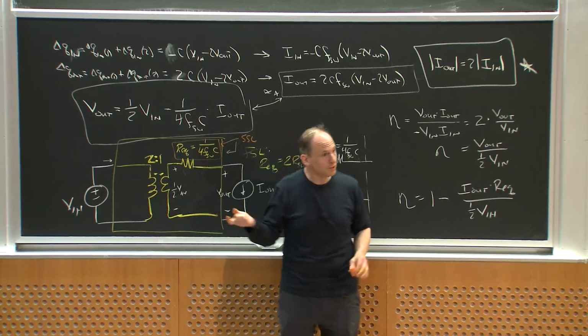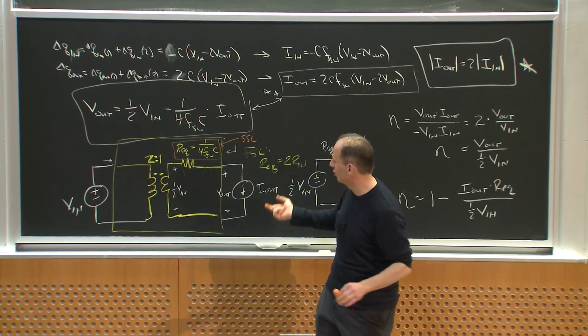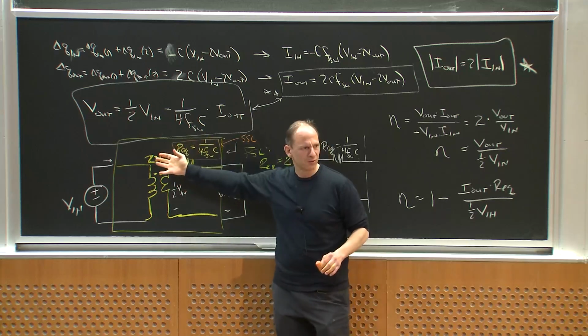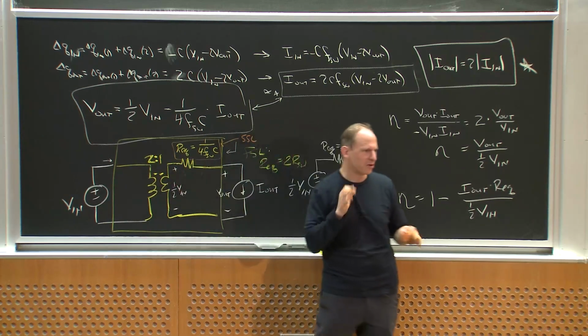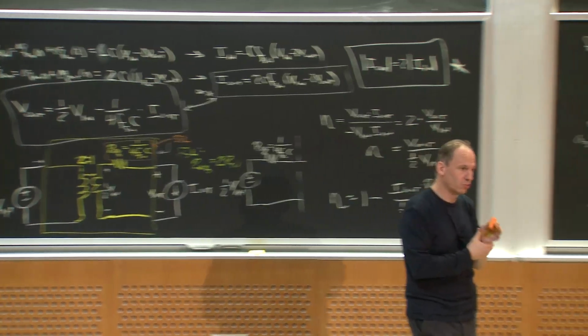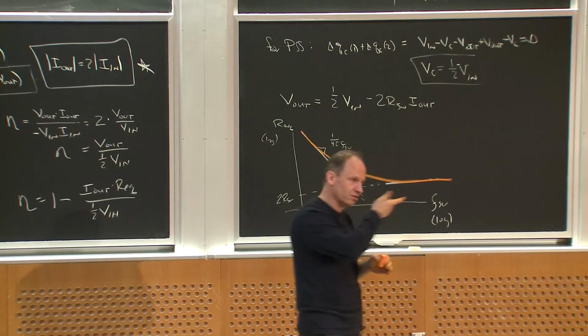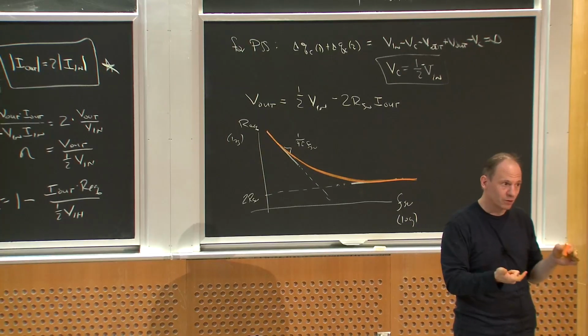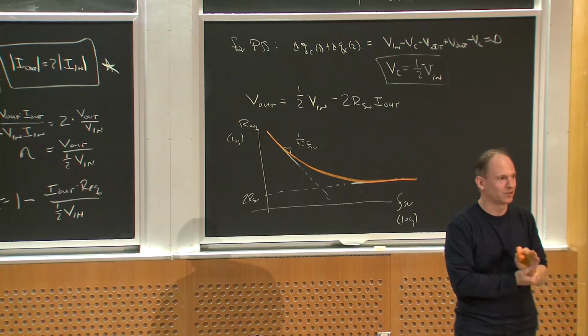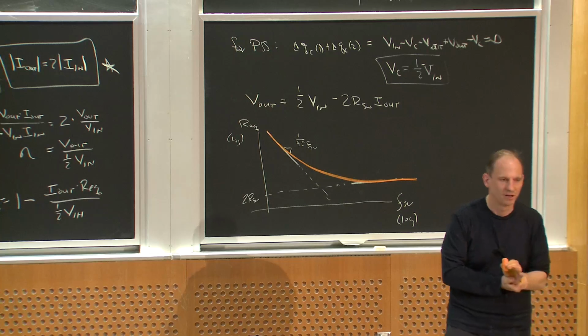Even in the slow switching limit, you can change the conversion ratio, but you're doing it through a resistive drop. It's sort of like you have an ideal transformer and then a linear regulator. So you can always use switching frequency, or in the fast switching limit duty ratio, to change the conversion ratio, but not in a perfectly efficient sense of the voltage conversion ratio.